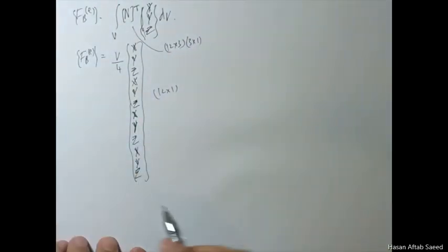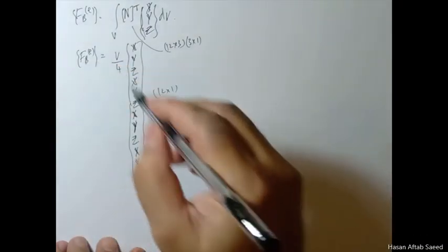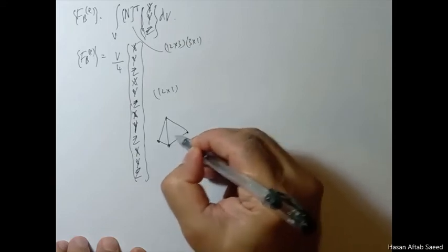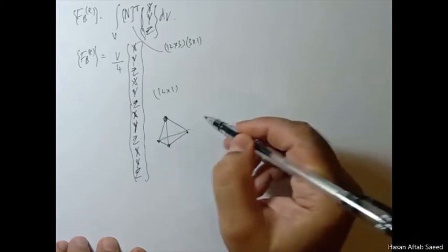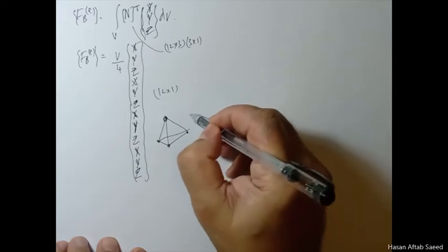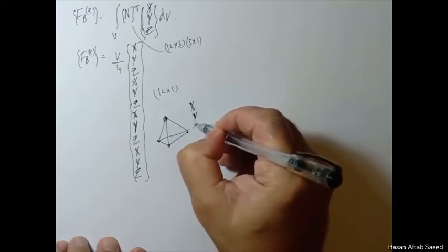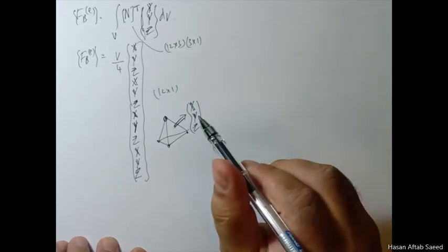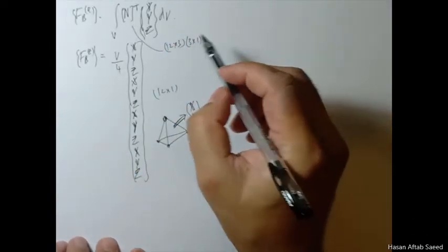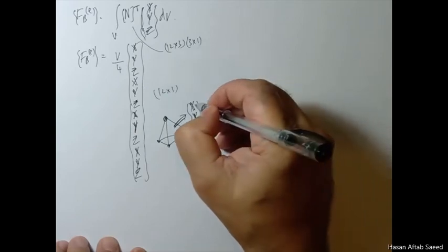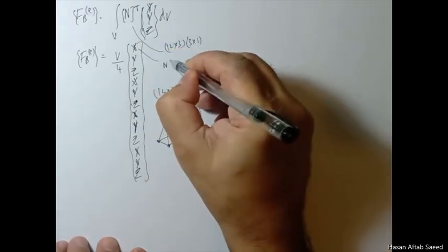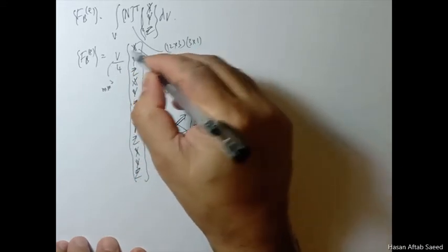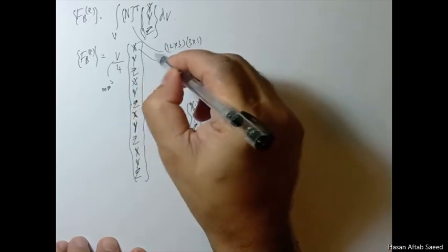Now let's talk about what this means. Again, very familiar. If this was the element and we're talking about some xyz force pulling it from this direction, this expression gives xyz in Newton per cubic millimeter, and this V is in cubic millimeter, so when you multiply them you get the total force in newtons.